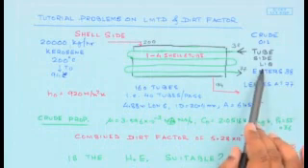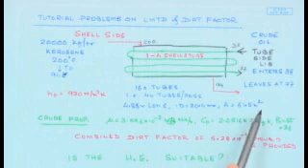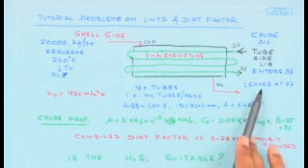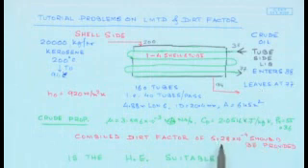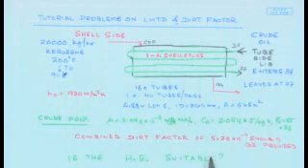That means, can these conditions handle a dirt factor even higher than this or a dirt factor lower than this. If calculations based on these data provide an overall dirt factor which is less than the dirt factor which is provided by the heat exchanger, then we have a problem.